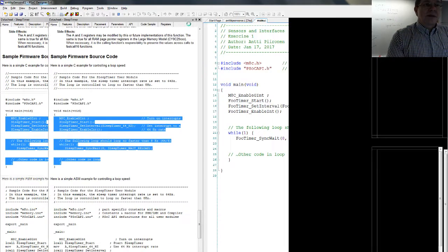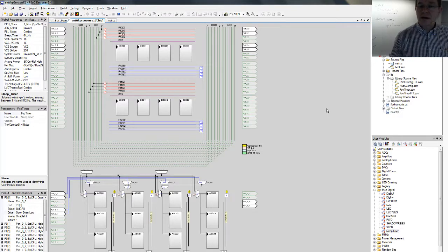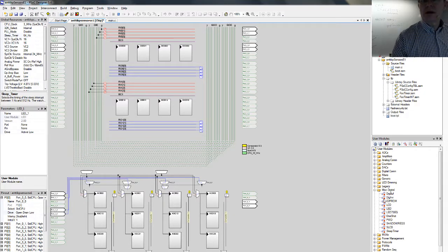Okay, but today you also need to make the LED there. That's simple. The same way as earlier. We include LED, just double clicking the LED module here. Okay. Clicking it here, actually then we can change the name. Okay, but maybe I will call it Blinky. Blinky. Okay, we call it Blinky. Now we can select the port pin and drive. Okay.